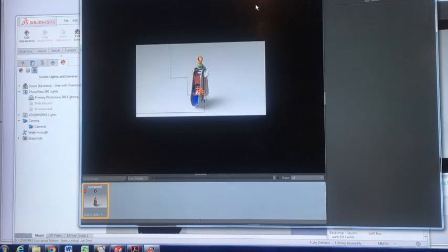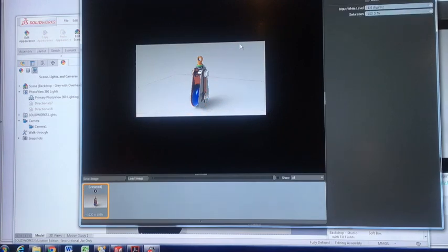So when you're rendering, some things to be aware of, things that slow down the render: any clear materials, because there's light reflection, refraction behind them. So where I've got this section here, it's a little bit slower. And lights, okay? If you have lights combined with clear materials, that can slow things down quite a bit too. So that sound you heard, someone else's screen, that's a render completing. All right, and there we go.